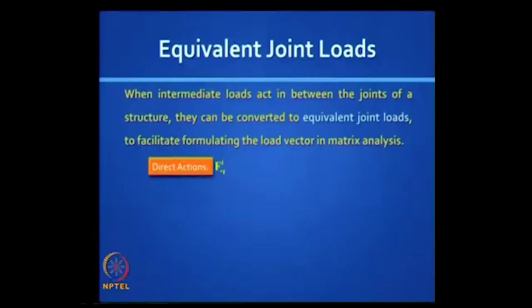So this notation F I star F, what does it represent in the stiffness method? In the ith element, the fixed end forces, that small subscript f stands for fixed end forces along the local axis. Okay, so it's a local axis system, right? You can get fixed end forces from another problem,